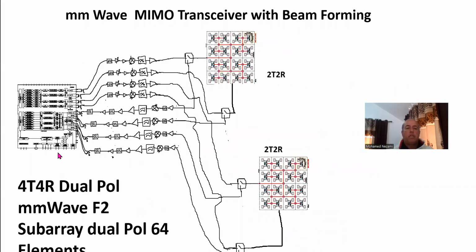So we took the sub-6G front section, the back end section, and we chopped off the section with the high power section, and then inserted an up converter and a down converter. And all we did is add a switch to switch between the feed network that feeds the plus 45 degrees, and then another network. Sorry, this is between the transmit and receive on one polarization and another one orthogonally on the other polarization.